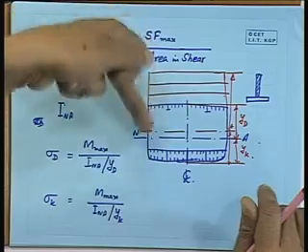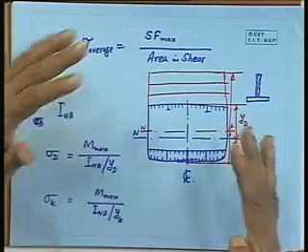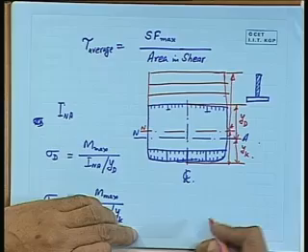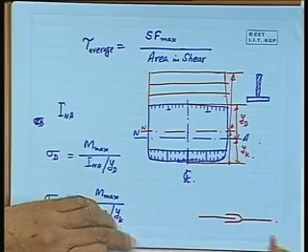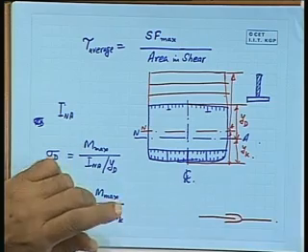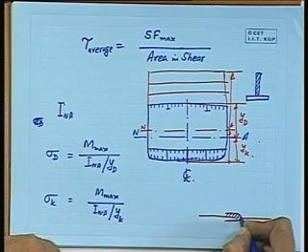So you are getting rid of this definition, and you are structurally changing the arrangement. And as far as the length is concerned, you try to give some sort of an expansion joint, which sometimes looks like this. You can have some sort of soft material, which can be a packing material here.